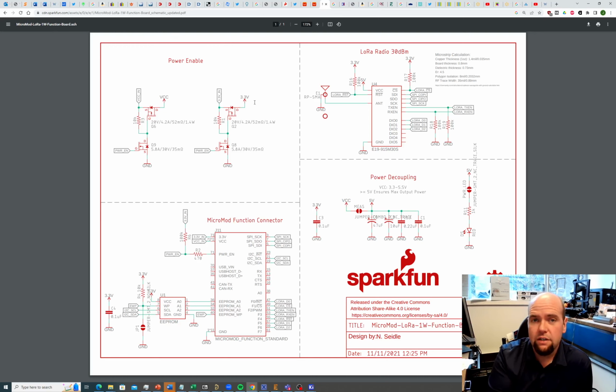So there are two power signals coming in: VCC, which is a high voltage, 5 volts, to drive the radio amplifier, and 3.3 volts, which just drives the circuitry and electronics. It cuts them both, and it's really important to cut both. If you're ever cutting power to something, you want to fully cut any power signal. You don't want one power disabled and the other enabled. So the same signal cuts both of these, which is probably the proper way to do it.